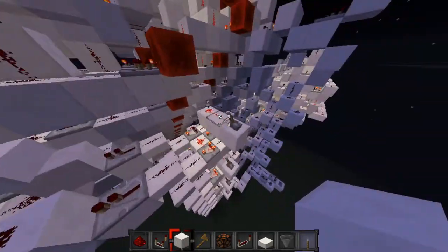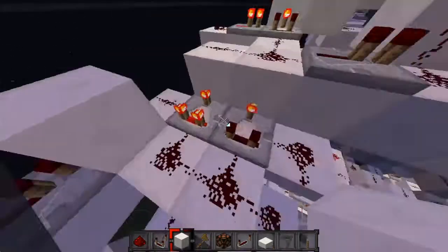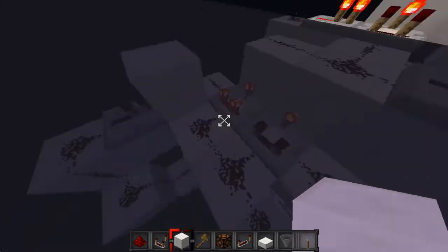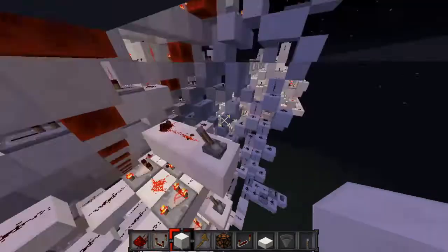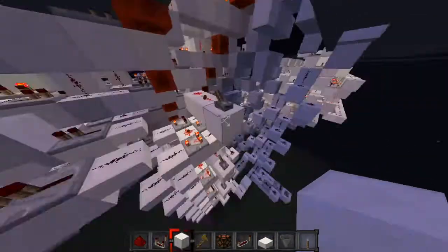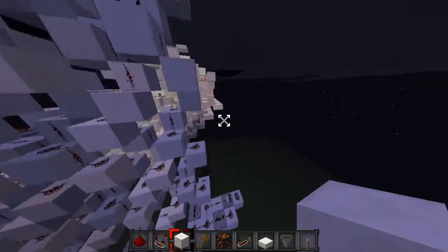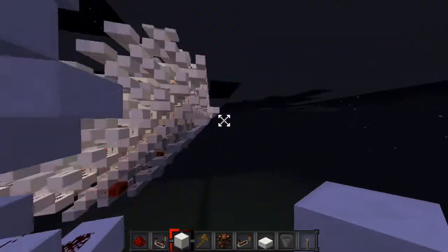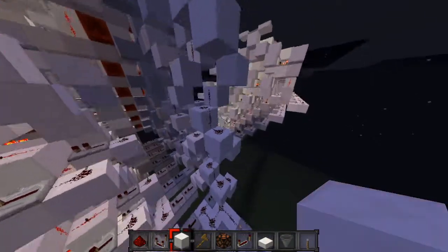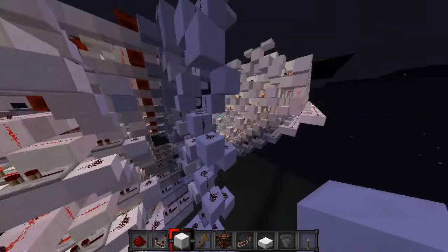And what I was trying to do before was I said, look at this XOR gate right here. It doesn't actually take any inputs from the memory, it just takes inputs from the barrel shifter. Whereas the barrel shifter will take one input from the previous clock cycle, and the number of shifts to be operated, that information is going to come from memory.